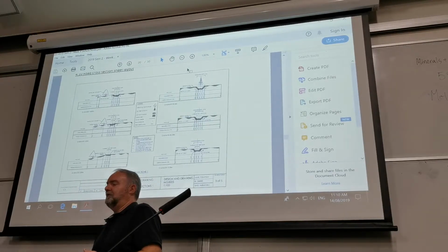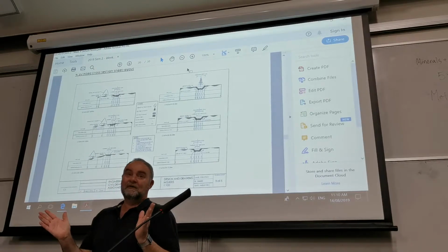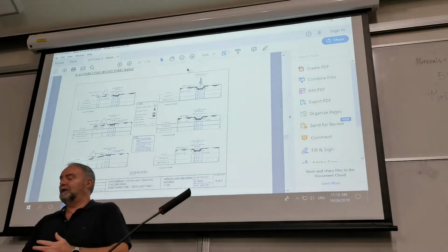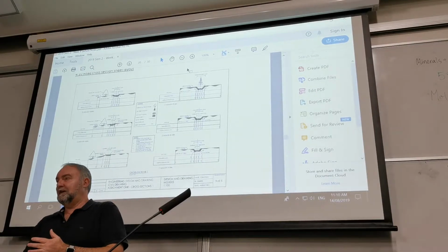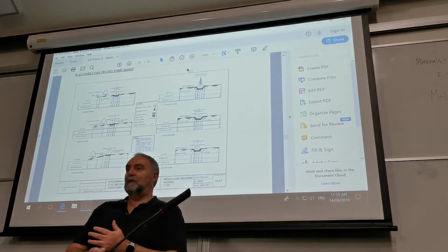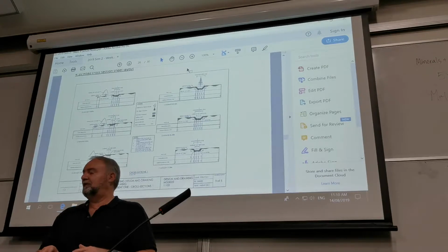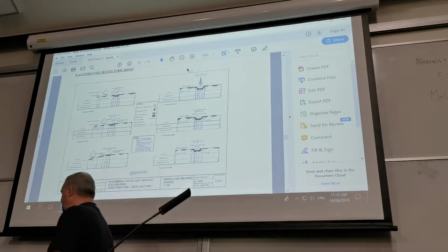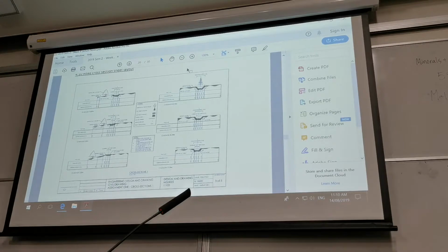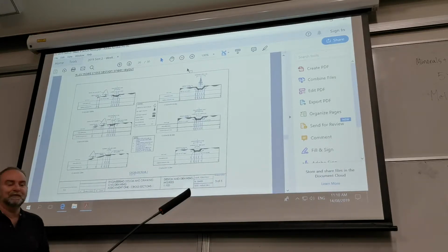Thirdly, the batter slopes will be back to 1:1. And fourthly, if we change our scale, our text and our arrows are going to change back to another size. And I don't want emails saying, what's the size of the text? Is it 0.35? Is it 0.7? On the very first lecture, over here on this board, a little bit to this side still, is the calculation that I did for the text heights. Please apply that to the new cross section at 1 to 50, not 1 to 100. I'm sure you all know what I'm talking about.